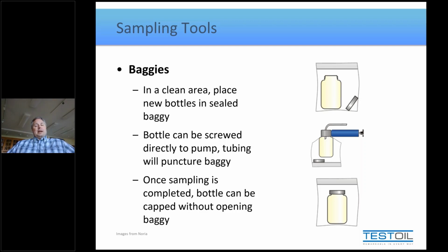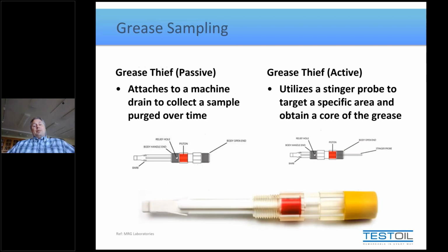One final note before we move on is if you have grease. A lot of people ask us about grease testing. And certainly, yes, greases can be tested very similarly to how oils are tested. But of course, the follow-up question is how do you get the sample? Well, we don't want you just scraping it off the outside of a piece of machinery and putting it in a sample bottle. That's going to be full of contaminants.